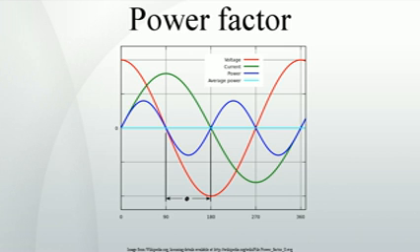Another electromechanical instrument is the polarized vane type. In this instrument a stationary field coil produces a rotating magnetic field, just like a polyphase motor. The field coils are connected either directly to polyphase voltage sources or to a phase-shifting reactor if a single-phase application. A second stationary field coil, perpendicular to the voltage coils, carries a current proportional to current in one phase of the circuit. The moving system of the instrument consists of two vanes that are magnetized by the current coil.